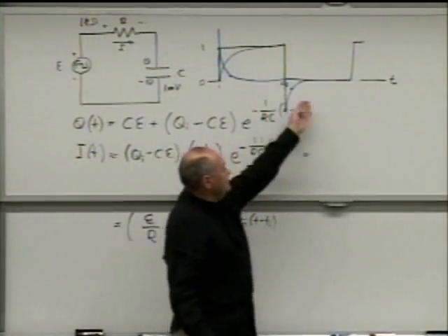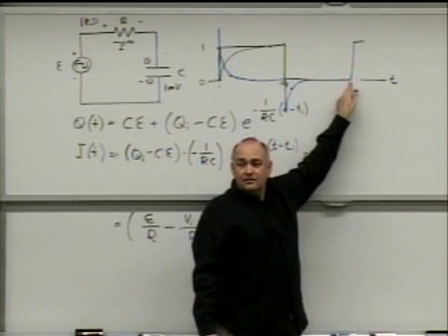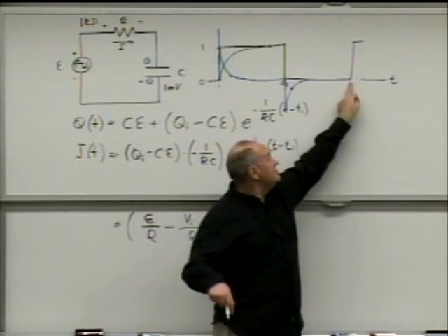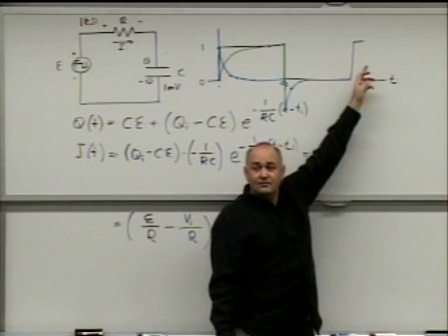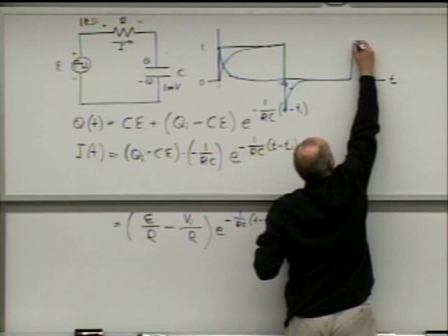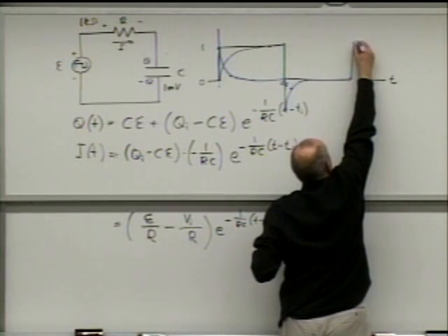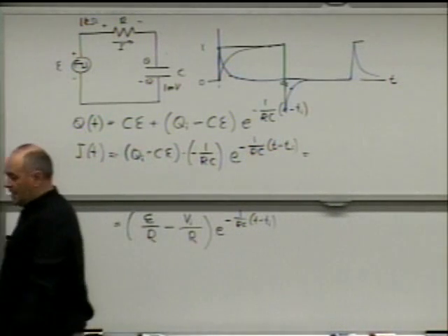And now the process repeats itself. Right now we have again voltage across the capacitor to be 0. Electromotive force jumps to 1 volt, and current is going to jump to 1 milliampere and asymptotically approach value 0. All right.